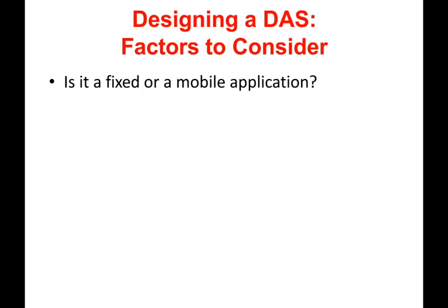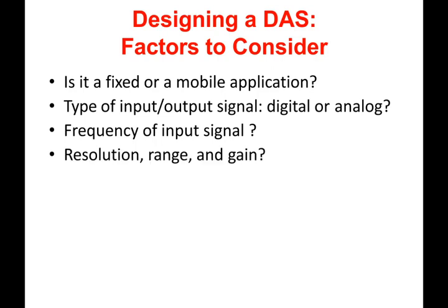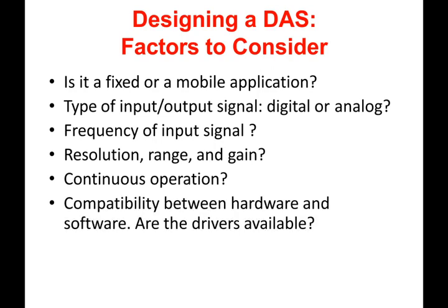You need to consider whether you want a fixed or mobile application, whether your input is digital or analog, what is the frequency of the input signal, what is the resolution, range, and gain you want to have, is it a continuous operation or does it stop somewhere? Is it compatible? Do you have compatibility issues between your hardware or software, or are the drivers essentially available? And the overall price, of course, is a very important factor in your design.